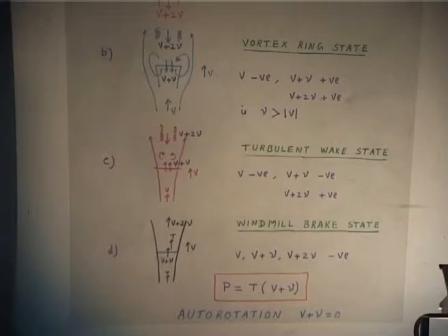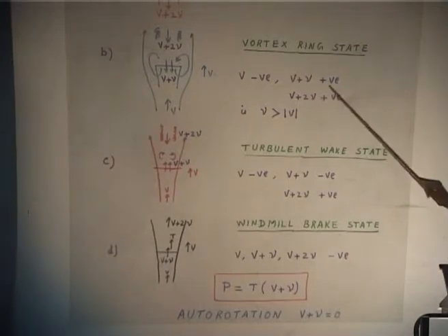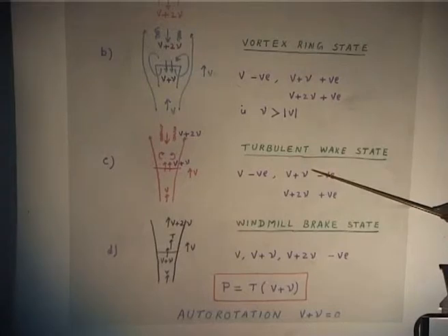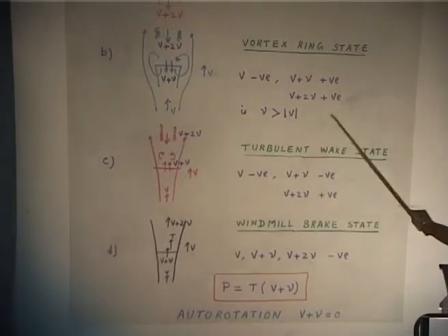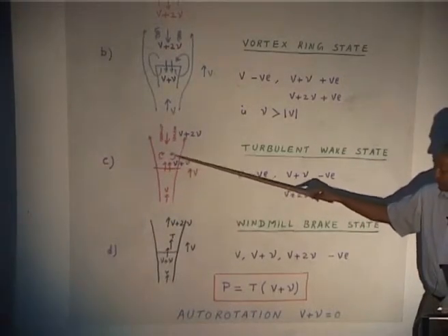but I am still supporting the weight. Please understand, power means the induced power. I do not supply any power, I do not require power, but I will be able to support my helicopter. That is between these two states, that is the boundary line, because V plus nu positive, you come here V plus nu negative. And in this state you see the flow here is up, here also is up, but